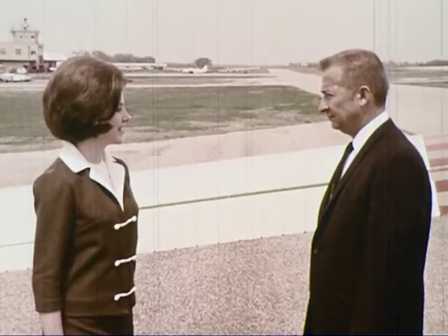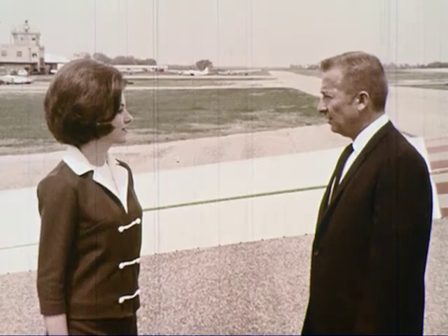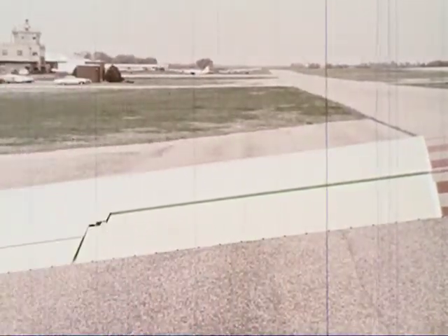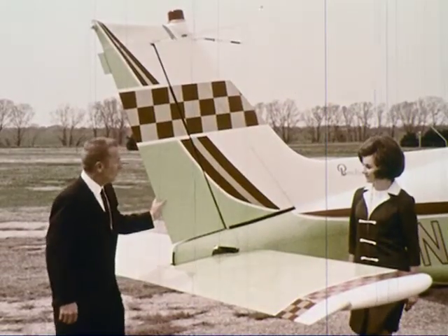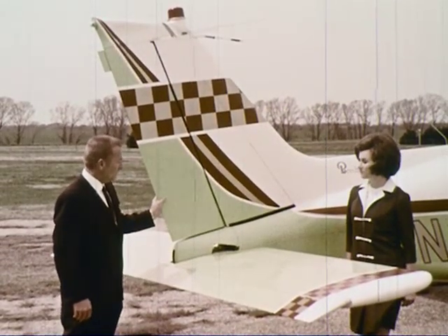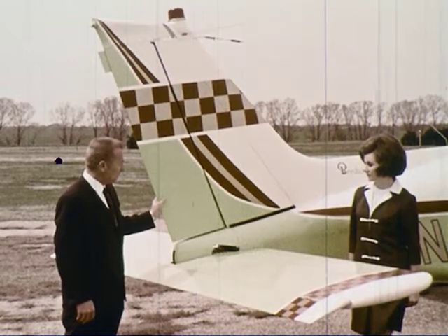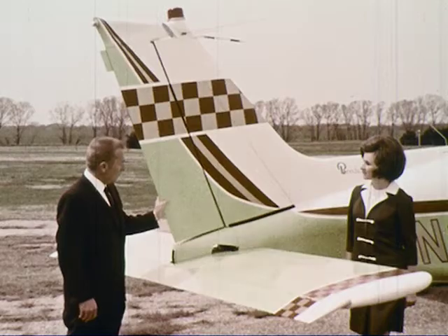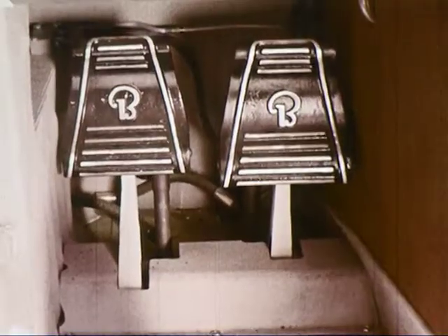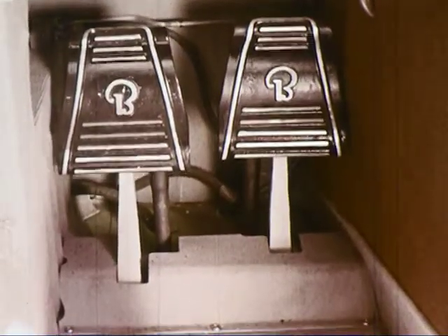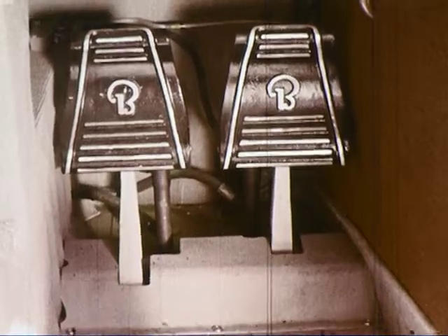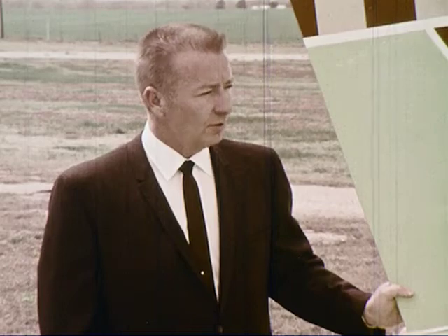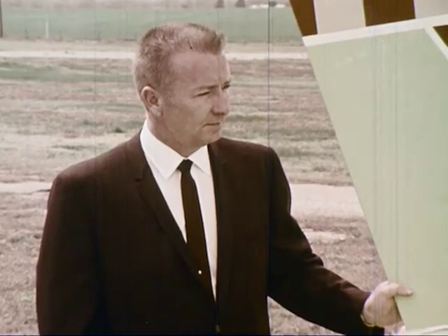I thought the tail did that. Well, it does in part, but let's take a look. In order to make what we call a coordinated turn, the rudder and aileron are applied at the same time. The rudder is moved by the rudder pedals on the cabin floor. Aren't the rudder pedals also used in steering on the ground? Yes, they are. You push on the rudder in the direction you want to turn.